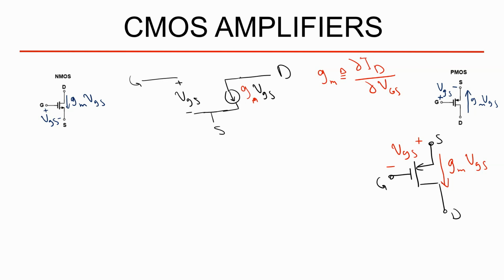This is a really great point to notice, and I mentioned this from the book Fundamentals of Microelectronics by Behzad Razavi. And another thing, in this scenario we neglect the channel length modulation. If you add channel length modulation, you can just add this resistor between drain and source, which is called RO, or sometimes we call it R drain source. And R drain source is defined as 1 divided by lambda times I drain.